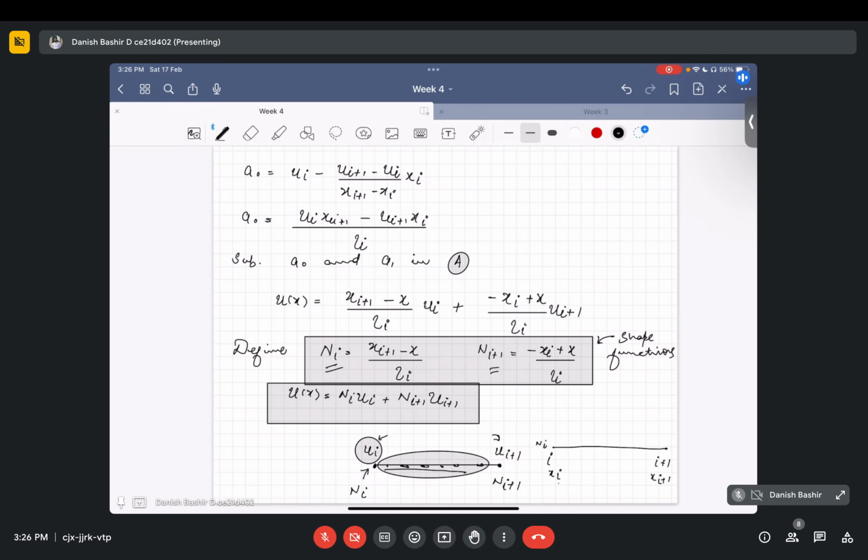So if I put xi here, Ni will be equal to (xi plus 1 minus xi) divided by li. Initially I told you that xi plus 1 minus xi is itself equal to li, the length of the element, so li divided by li equals 1.